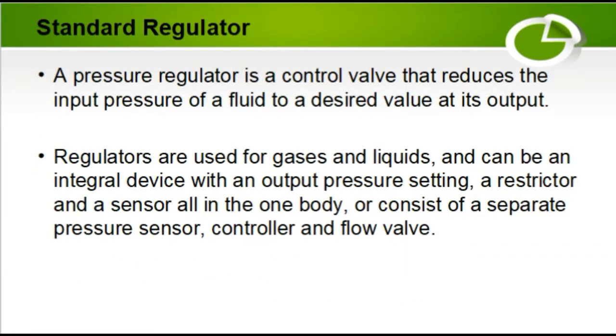Standard regulator. Standard regulator is a pressure regulator, a control valve that reduces the input pressure of a fluid to a desired value at its output. Regulators are used for gases and liquids and can be an integral device with an output pressure setting, a restrictor, and a sensor all in the one body, or consist of separate pressure sensor, controller, and flow valve.